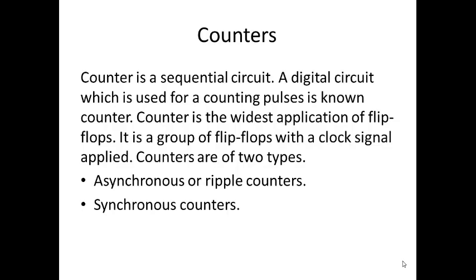A counter is a sequential circuit. It is a digital circuit for counting the number of pulses given at the input. In a counter we will be using flip-flops, a group of flip-flops. If it's a 2-bit counter or 3-bit counter, accordingly you will be using a number of flip-flops. All the flip-flops are connected to a clock signal.